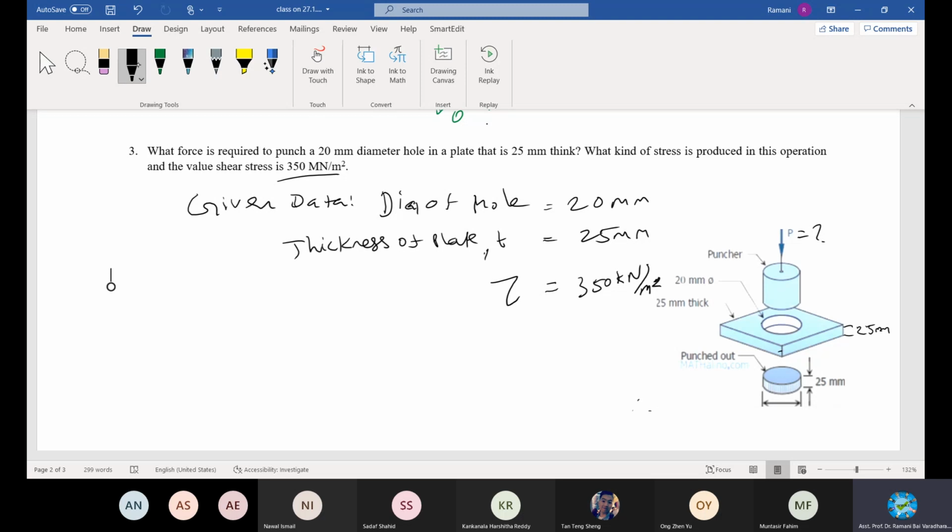You need only this area, not the surface area on top or perpendicular to the load. You need to ignore the area perpendicular to the load, because there is compression, but it is not significant compared to the shear stress produced. Okay, we need to find out how much force you can apply so that it gets sheared off. Solution.